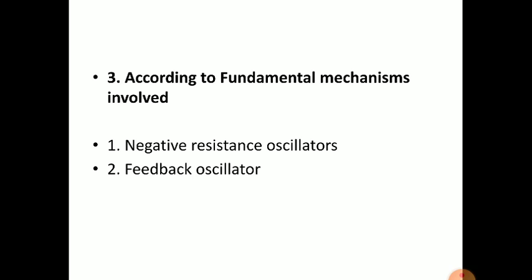But we can use another mechanism, the concept of negative resistance oscillation. Yes, there is a possibility of negative resistance, not a negative resistor. From a particular circuit you can get this property of negative resistance, but there is no negative resistor.